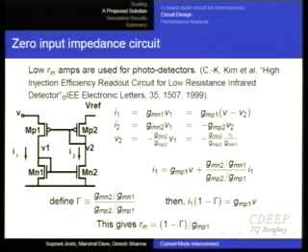So whatever Vref you have here, this voltage will be maintained at that. So therefore now we got that condition which we wanted, that the interconnect is maintained at a constant voltage. Now let's see what happens to the current. So we are forcing a current. Suppose there is some current source driver from the other side. So the voltage is held constant, but some small signal current change is being sent. So let us do the small signal analysis of this.